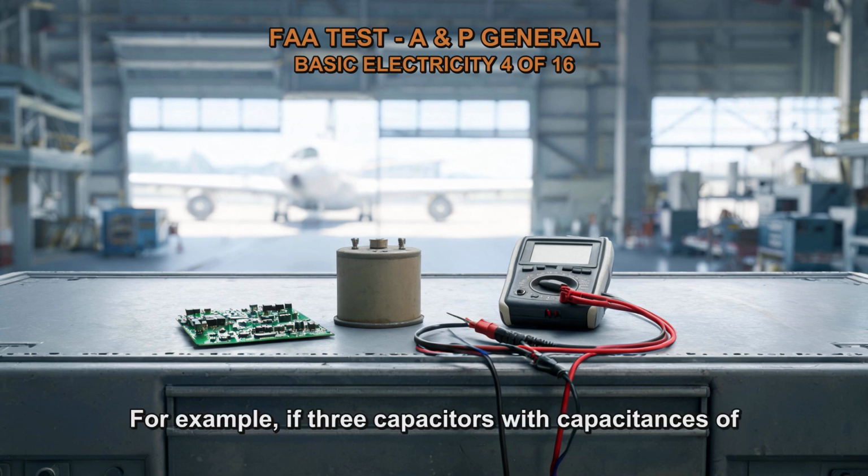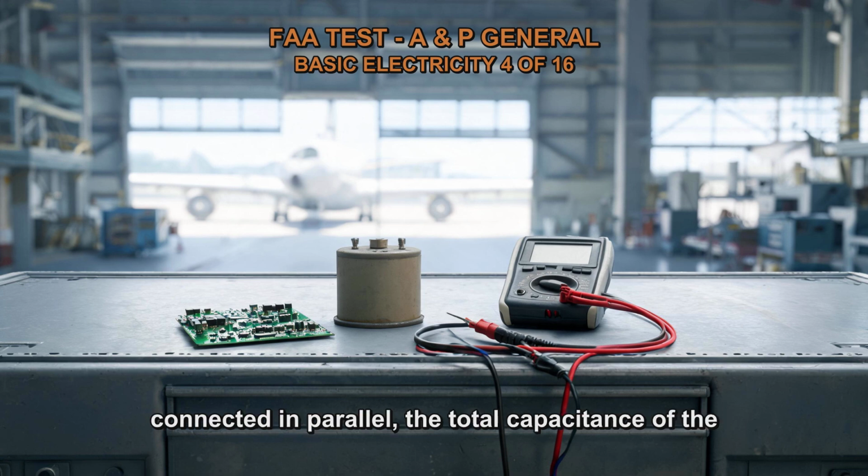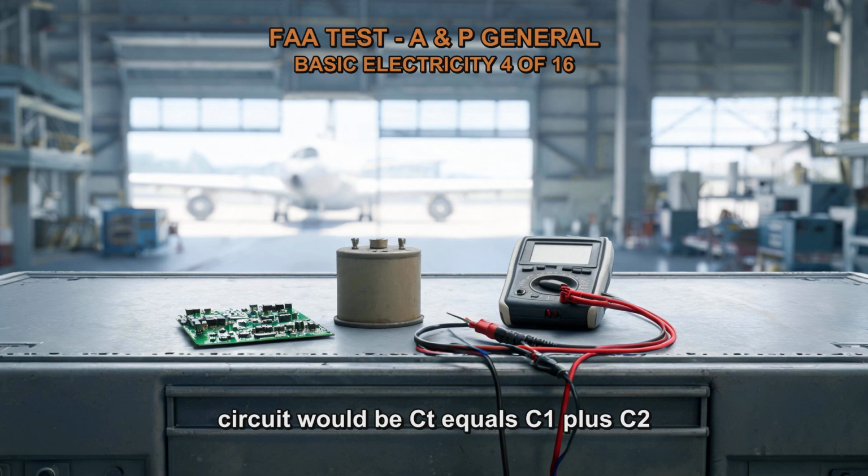For example, if three capacitors with capacitances of 1 microfarad, 2 microfarads, and 3 microfarads are connected in parallel, the total capacitance of the circuit would be CT equals C1 plus C2 plus C3. CT equals 1 microfarad plus 2 microfarads plus 3 microfarads. CT equals 6 microfarads. So the total capacitance of the circuit is equal to the sum of all the capacitances, regardless of their individual ratings.